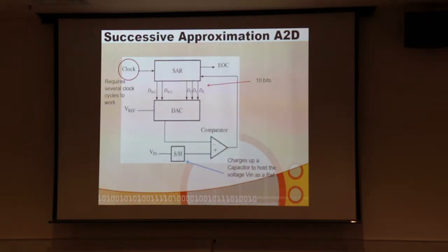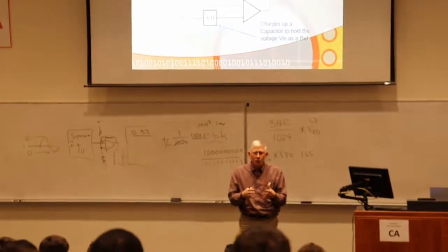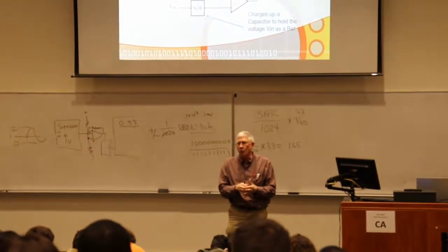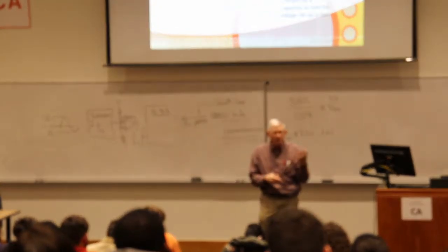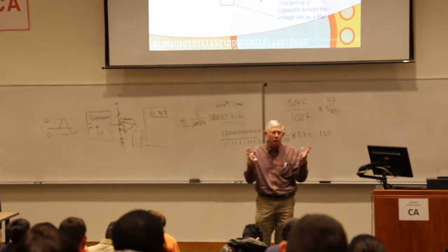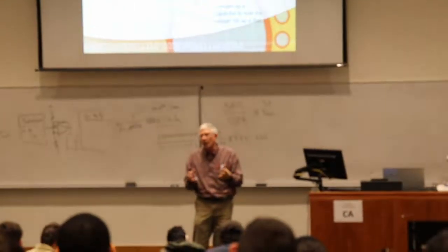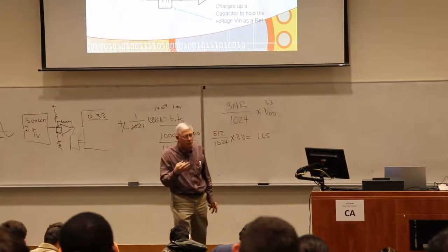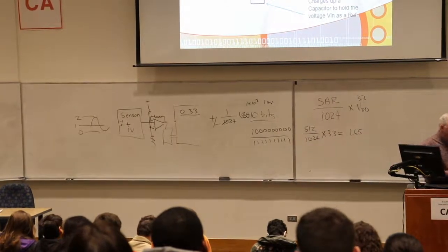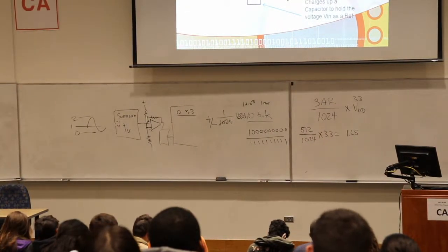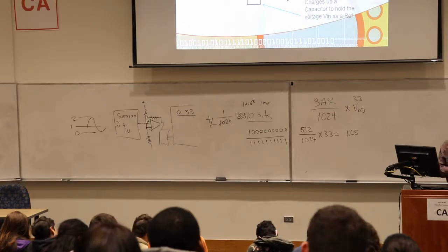And that's one of the reasons why the latency on the response time for interrupts is so important. We don't want interrupts taking variable amounts of time to execute. We want them to be very fixed so that we don't introduce all this extraneous jitter signal into the things we're trying to sample, especially when we're trying to go to a little higher frequency. And then for digital signal processing chips that are running at video levels, those become huge, big deals.